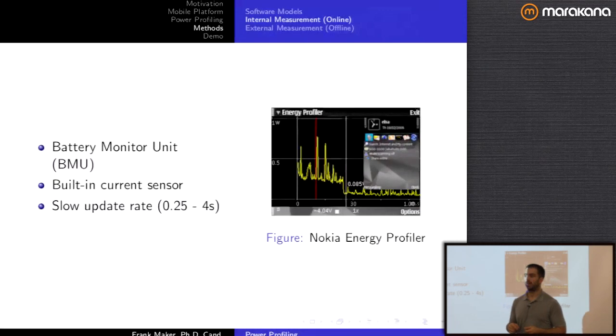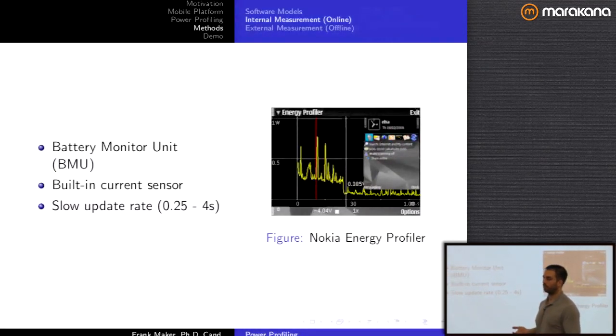In order to do that, it has a little current sensor inside it, which measures the current and then feeds that into the model in order to give you a good estimate of how much remaining battery life you have. Because the system needs to know how much battery life you have in order to shut down cleanly if your battery life goes too low.